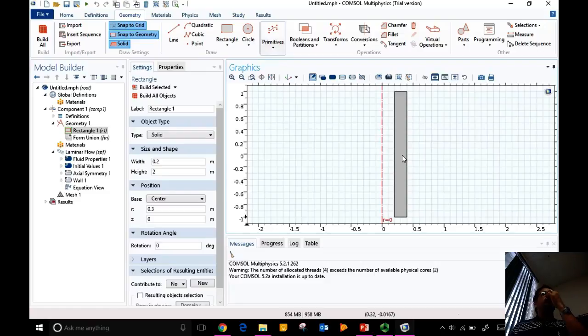Any other questions? See, these are questions that really give you a practical insight on how to go about formulating various problems, and through assignments we will reinforce that. Okay, so the problem I want to solve is concentric cylinders, infinitely long cylinder, so you need to keep that in mind. And I want to first generate the 1D flow and then see whether I can force it into the 2D flow. I'm going to have difficulty in convergence, but you will know how to set it up.